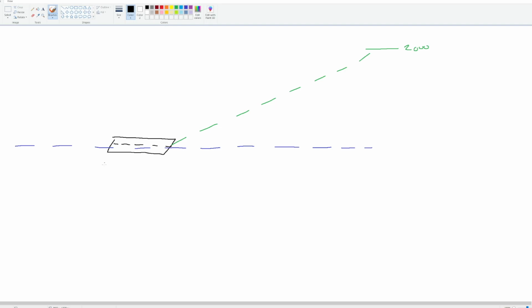Good. So the thing is, the barometric reference, a QNH, is based upon the mean sea level pressure. Good. So if we change the QNH setting on our altimeter, we can have, for example, let's say we set another QNH, we can actually move this barometric reference.